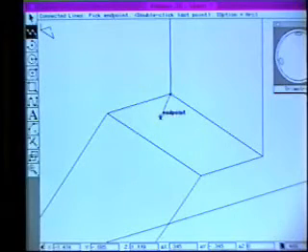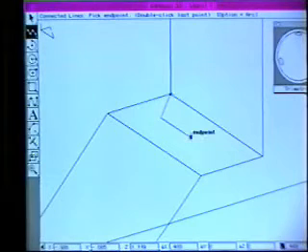And then what I want to do is go in and begin some lines right here. So I'm going to drag a line, and notice it says align 45. So I do want to go along that 45-degree angle, which is flat along the bottom, and then I will come across along the x-axis. And then I know that if I hold the option key, I temporarily get the arc tool, and I can pull an arc along a 45-degree line, which gives me a quarter circle arc.